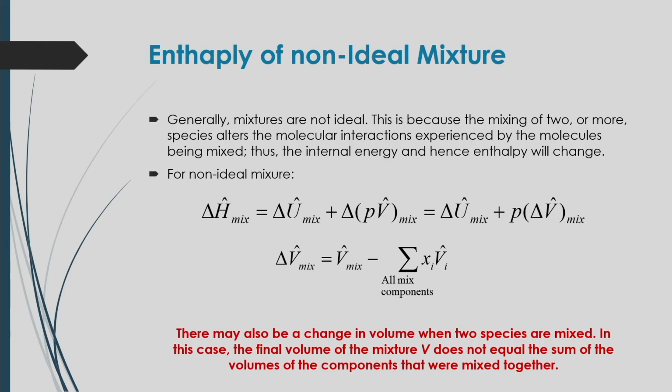And for a non-ideal mixture, the enthalpy change can be represented as the specific internal energy change of the mixture, plus the change in flow work or flow energy for that mixture. So, we can express it by this equation that is given in the slides, and in this case